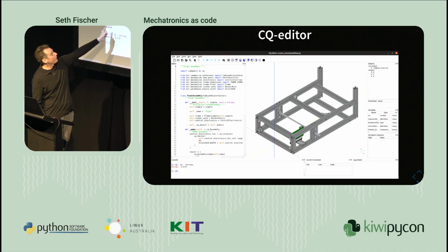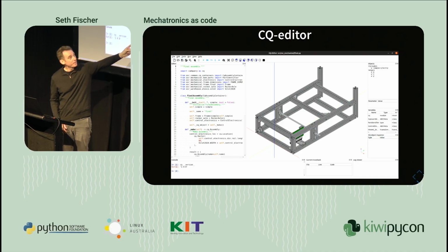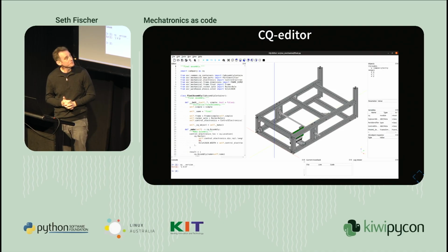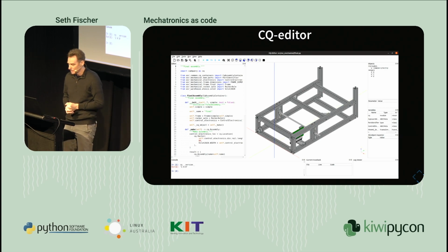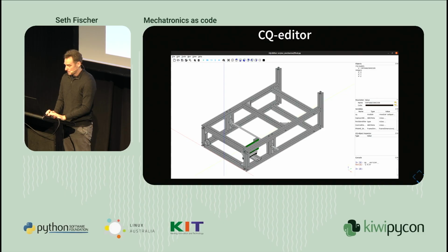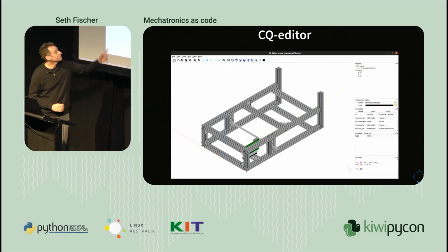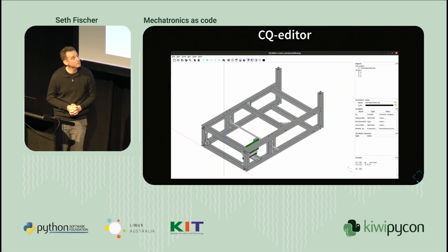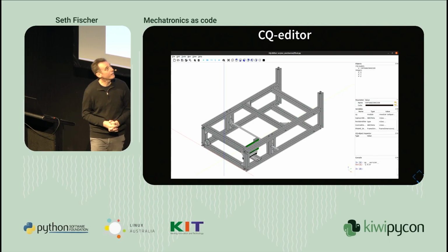This code runs and outputs this robot frame, which is actually the beginnings of a model Mars rover. Now, I prefer not to use the editor within CadQuery editor. I use PyCharm, so I close the editor and work in PyCharm and just do the visualization here in CadQuery editor. It's got some useful debug panes and a console.